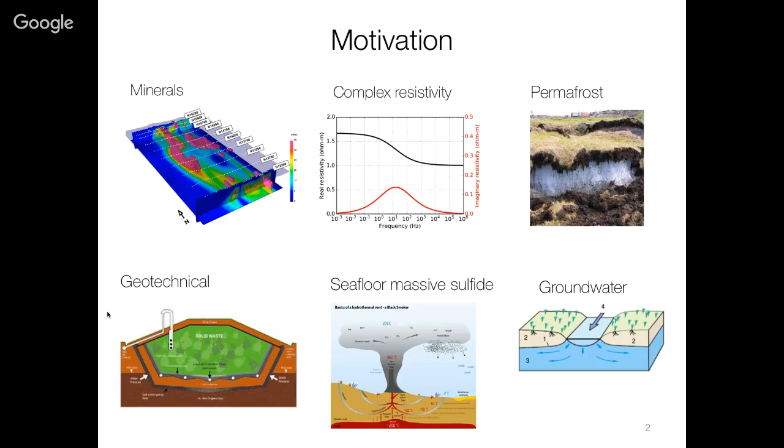And all of these are kind of bound up with the fact that the electrical conductivity actually is frequency dependent. So if we measure the electrical conductivity in the lab, generally you have a block of material, you put a voltage across it at a certain frequency, and you measure the current, and then that ratio gives you the resistance. If you change the frequency, you get a different number. So electrical conductivity or resistivity actually depends upon the frequency, and so it's regarded as being complex.